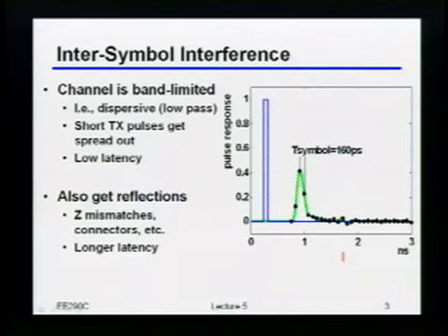In particular, the way to see that, all of these black dots here are what would be the voltage you'd get at the clock-spaced, or bit-spaced, samples. So what you can see is that even though you may have sent, from a bit standpoint, 0, 1, 0, by the time it arrives at the receiver, you have 0 here, but some stuff over here, a pretty attenuated signal here, still some residual stuff here, and so on and so forth.